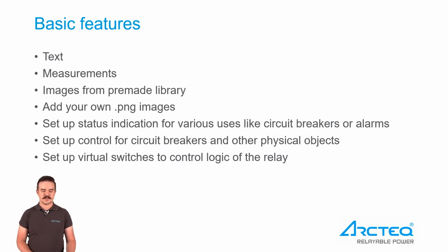You can set up a status indication for various uses like circuit breakers or alarms, set up control for circuit breakers or other physical objects, and then also set up virtual switches to control logic of the relays, which means changing the setting groups, blocking protection functions from tripping, or other functions like that.